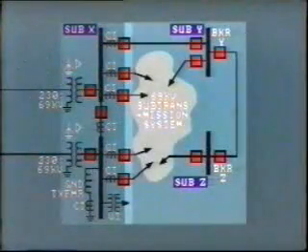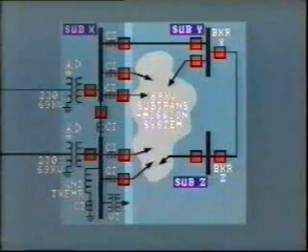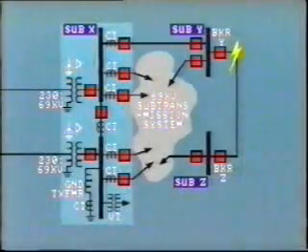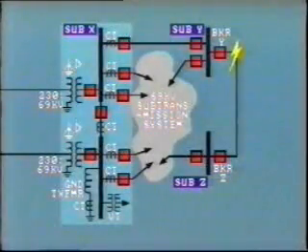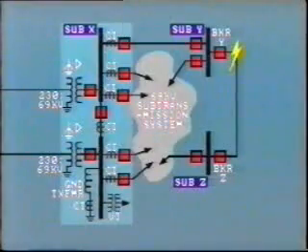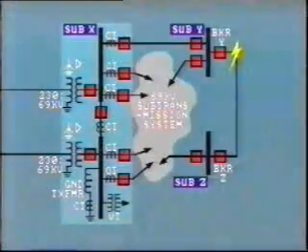Our next case history, case 2, shows what happens when the nature of the fault itself changes during the disturbance. Here we have a fairly extensive 69 kV subtransmission system that experiences a fault on the tie line between substations Y and Z. The 69 kV system is delta connected, but effectively grounded through zigzag grounding transformers located at substation X. Notice that all the oscillograph equipment is installed in substation X, remote from the fault location. In spite of this distance, we can still obtain a great deal of information from the recordings.